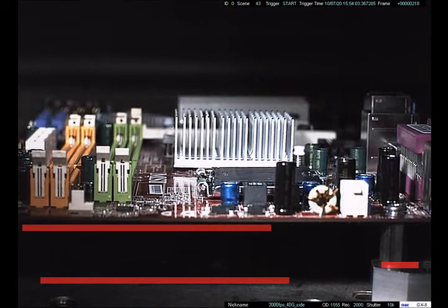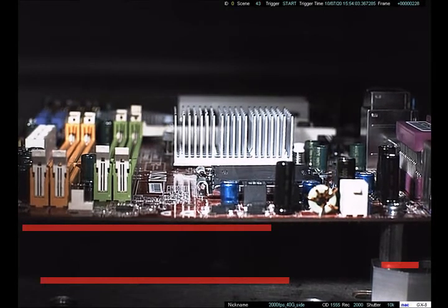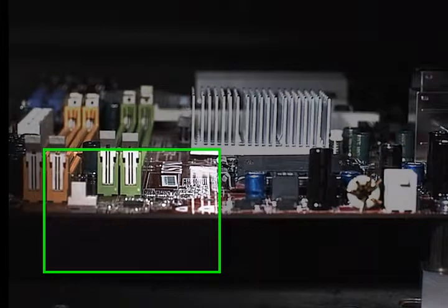As can be seen here, the displacement of the table and fixture for the PCB are very low, but the board's response is much higher. As the board flexes, strain is induced in all the solder joints, particularly for the rigid surface mount components.